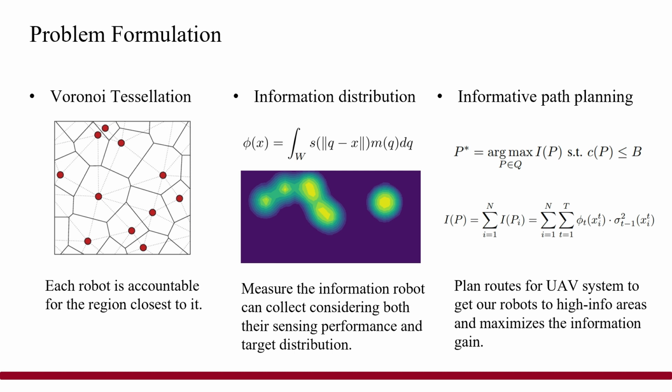We estimate the information gain throughout the mission by multiplying the information value by the uncertainty of the robot estimation. This is because as we observe an area over time and gather sufficient samples, with the increase of certainty, the information gain decreases. At this point, it is crucial to explore new areas with high uncertainty, seeking new high information regions and observing new targets.